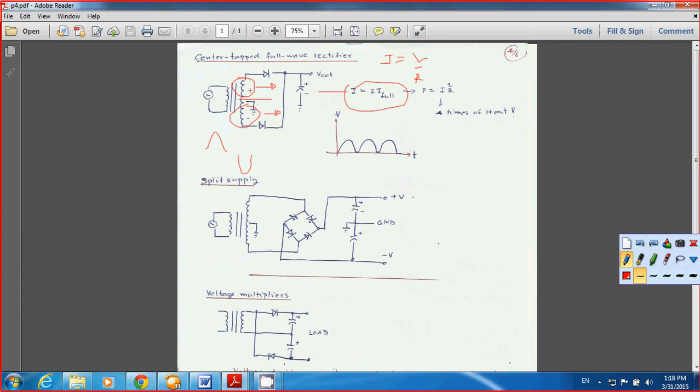And the main problem is that you have a double current here. And if you compare to power, P equal to I square R, what happens? When you have double current, and this term is squared, you have 4 times the heat. So in practice, it doesn't work. That's why we use the full bridge rectifier instead. And that's what we call, as I mentioned earlier before. Okay.